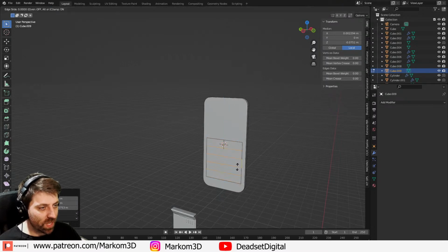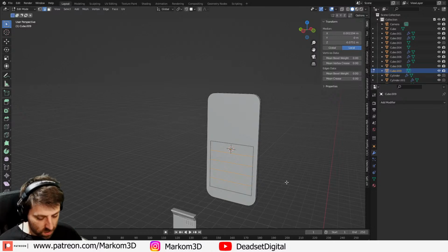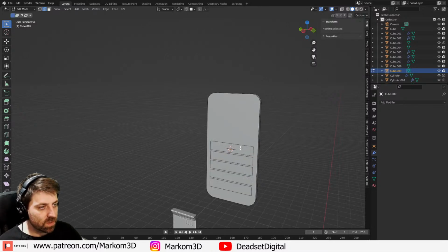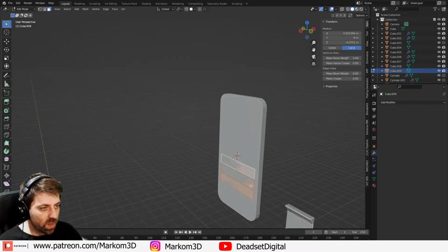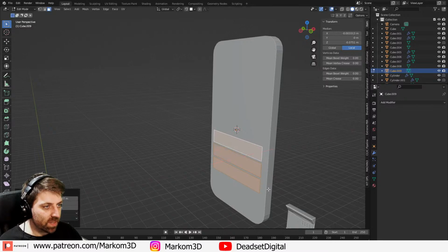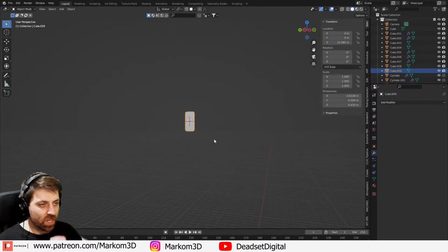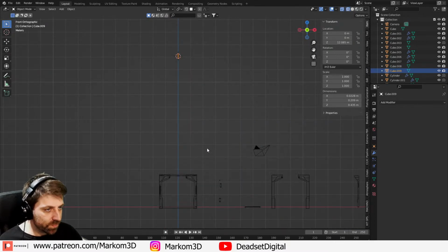And we're going to put a few edge loops in there. Let's do a few of these. Delete faces. Then I'm going to select these. Delete faces. And then with these selected, let's go GX, E to extrude, delete faces. And so that's kind of like our initial piece for our handles.